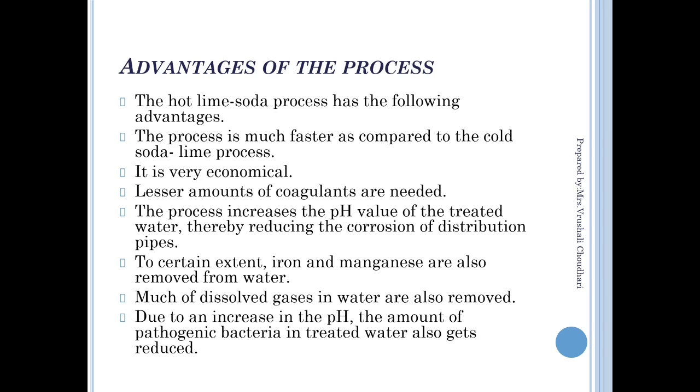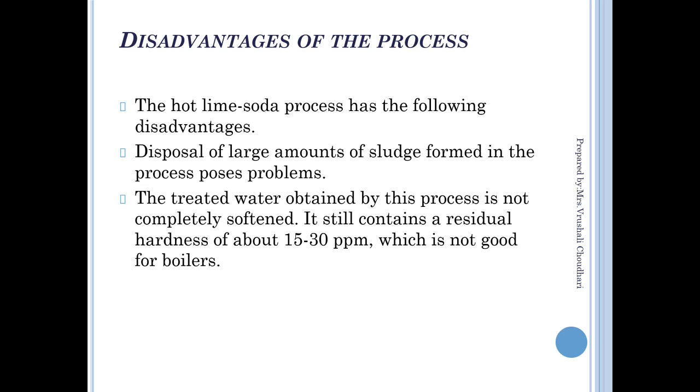To a certain extent, iron and magnesium salts are also removed by this process. The dissolved gases are also removed by this process, so the rate of corrosion decreases. Due to the increase in the pH, the amount of pathogenic bacteria in the water also reduces. As the pH increases, bacteria get killed.